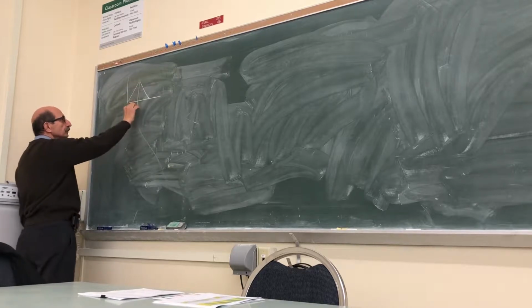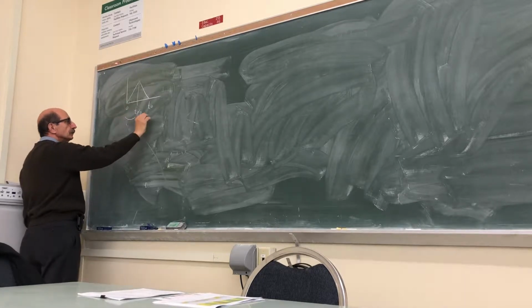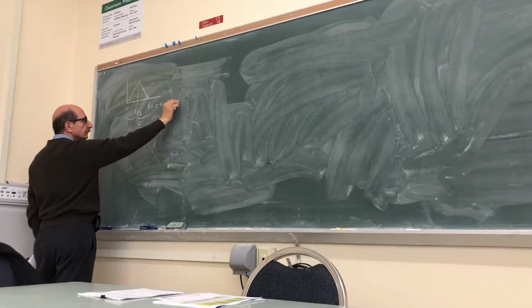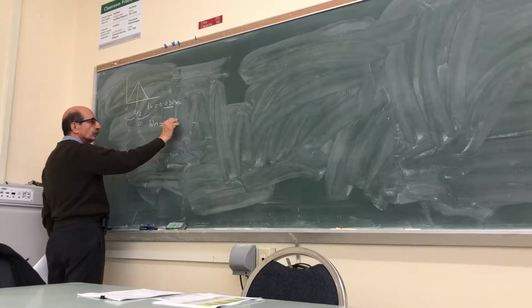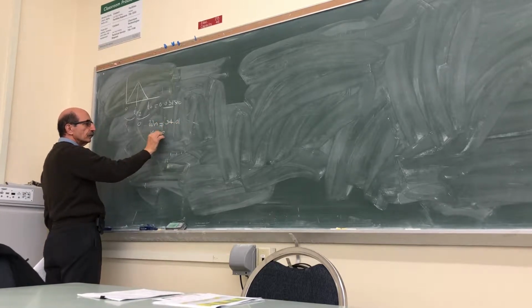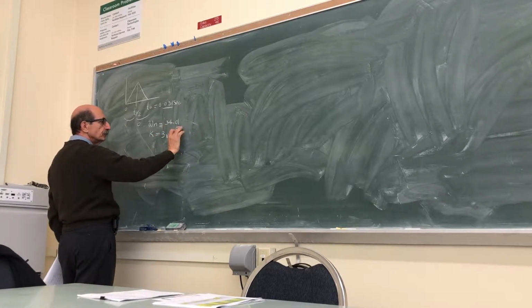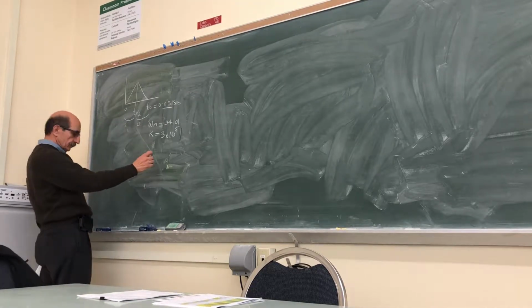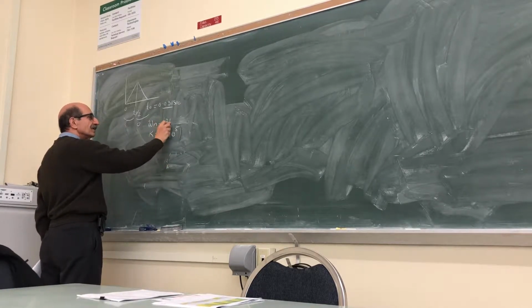We had this loading, T0 over 2, T0, 0. T0 was 0.031 seconds. So we derived the natural frequency, which was 34.01. The stiffness, if I remember, was 3 times 10 to the 5 pounds per inch. What else? Wasn't natural frequency 31.05? I have 34.05. 34, okay. Yeah, that's what I have as well.